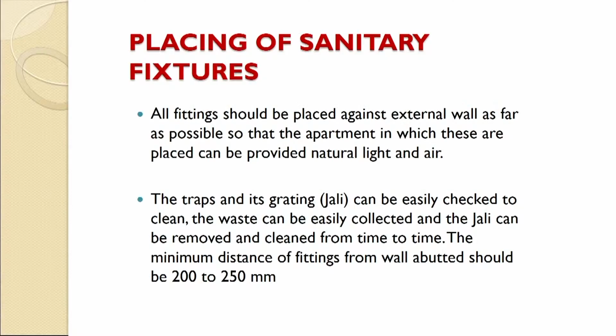When you are placing any fitting, you should remember that traps or jali, which is an important part of any toilet or wash basin, should be checked, cleaned, and the waste can be easily collected. Sometimes you are working in your kitchen and your wash basin gets clogged.